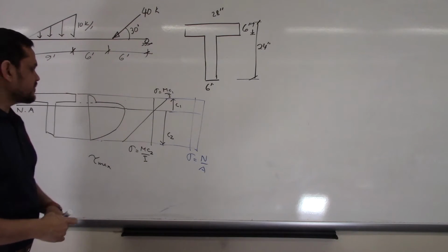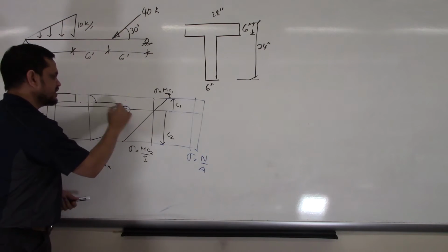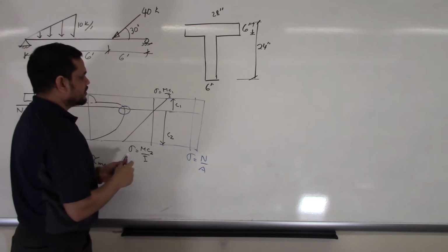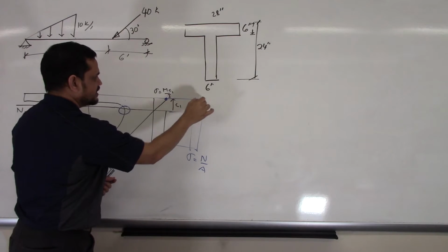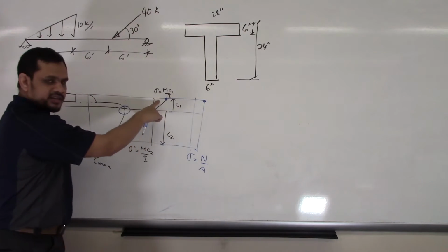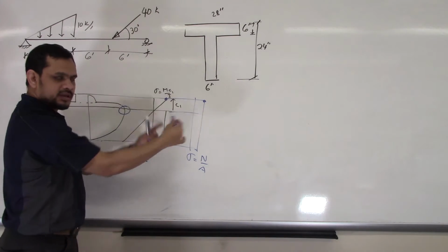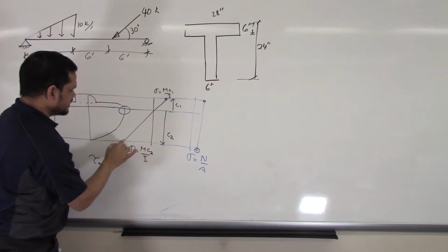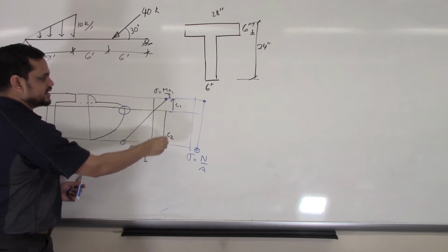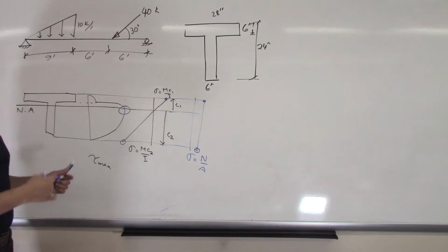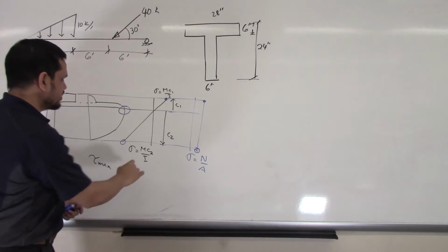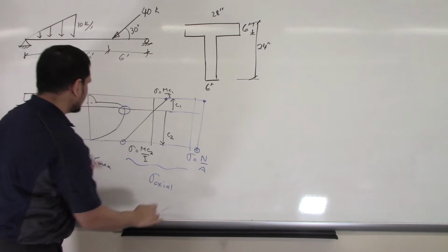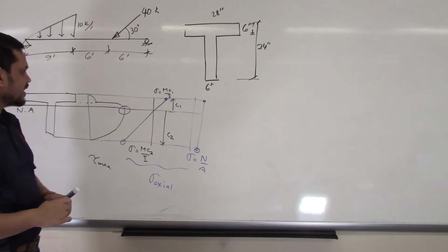So what is our objective? Our objective is to find this maximum shear stress. Then the summation of either this value and this value, bending stress plus normal stress, is the axial stress. Then we will find this value and this value, compare the two sets, and see whichever is greater. So this is axial and this is shear stress. We will find that.